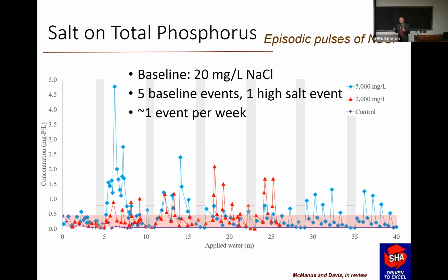We spent some time trying to figure out what's going on. The turbidity looks like it's related to suspended solids washout due to some colloid destabilization. The phosphorus is unclear. We had some trouble trying to speciate it because many of the samples were just so turbid we couldn't get good phosphorus measurements out of this. So it's something that at this point is somewhat preliminary, but we saw these phosphorus spikes as well as other spikes every so often after we added these intermittent salt concentrations.